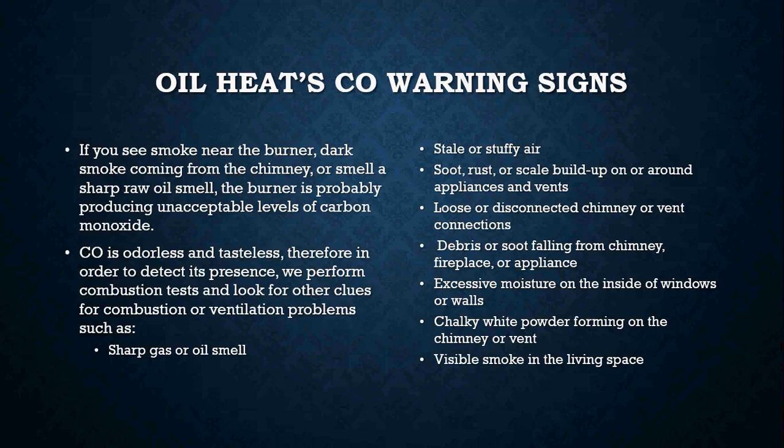CO is odorless and tasteless. Therefore, in order to detect its presence, we perform combustion tests and look for other clues of combustion and ventilation problems, such as a sharp gas or oil smell, stale or stuffy air, soot, rust, or scale buildup on or around an appliance and vent, loose or disconnected chimney or vent connections, debris or soot falling from the chimney, fireplace, or appliance, excessive moisture on the inside of windows or walls, chalky white powder forming on the chimney and vents, and visible smoke in the living space.